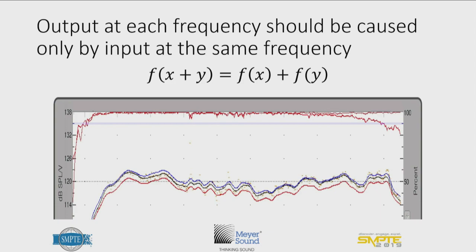There is signal at the microphone, which is not caused by the input to the speaker. And that is nonlinearity, and that's something that we want to watch out for, and it's one of the reasons for putting this microphone so close, to be able to see the effect of distortion on coherence without the effects of background noise and other sources of coherence reduction.